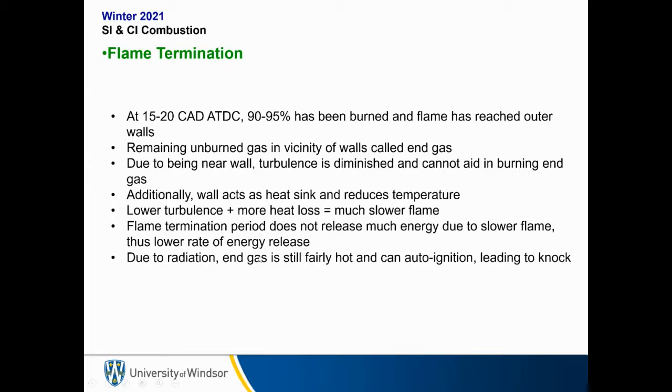And due to radiation, the end gas is still fairly hot and can auto-ignite, leading to knock. So in other words, we don't want to have a ton of end gas left in our cylinder because we're not going to get much energy release from it. But it can still auto-ignite, which leads to knock, which we definitely don't want.